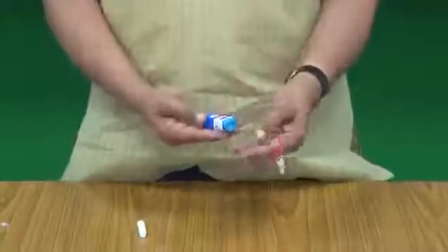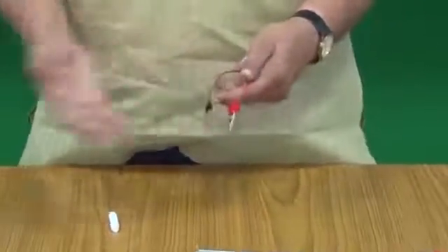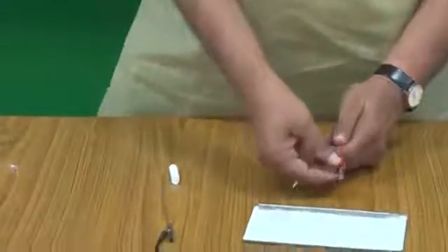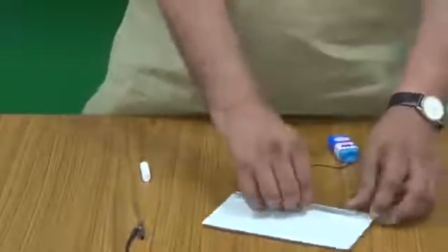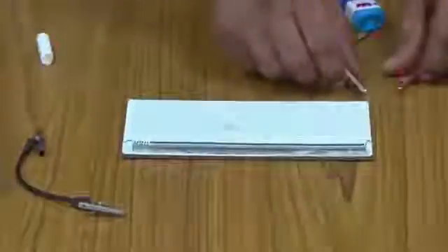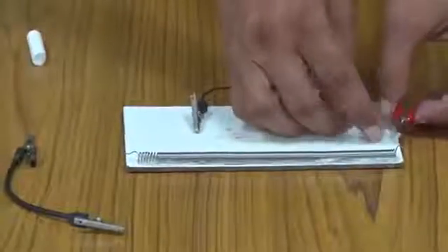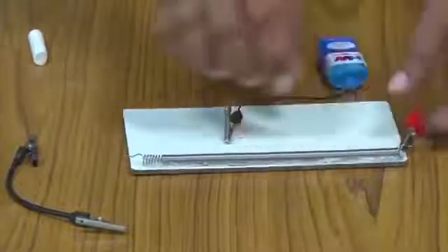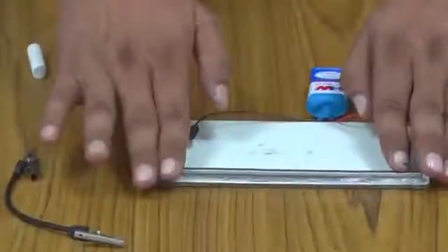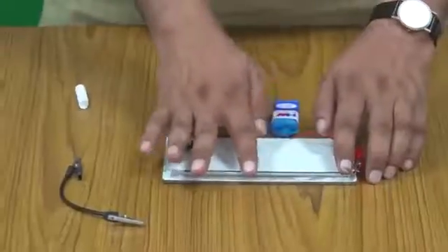So, I have this 9 volt battery, but I cannot give this 9 volt to the LED, it will just blow. I will talk about that a little bit. What I am doing is I have taken this wire, this is a heater coil, and I will connect this battery at the ends of these two wires. One I am connecting and one I will connect when needed. So, this will go here. So, this whole 9 volt is dropped across this, and then I can take a part of it, smaller voltages, from here.